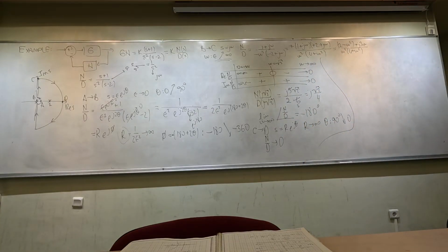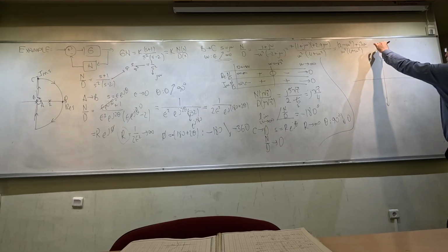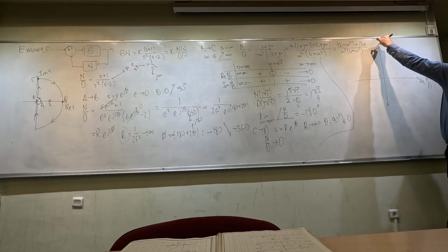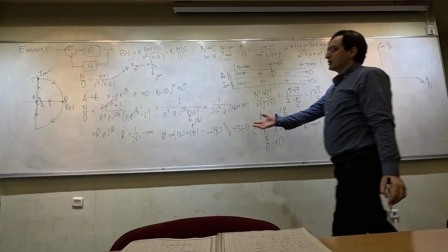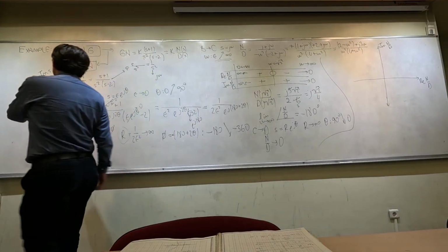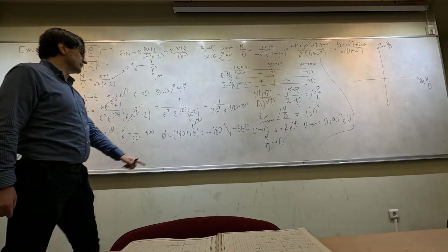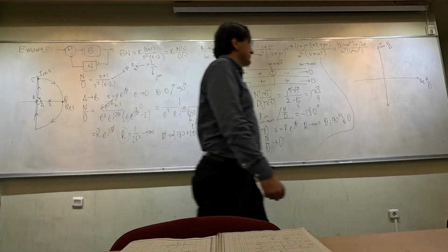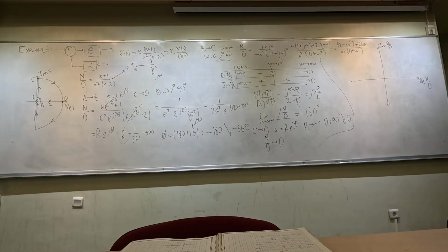And now we have completed the analysis for all parts of the Nyquist path, and now I'm ready to draw this thing. So I have real of N over D here and imaginary of N over D. We are going to start from the point A. Point A is going to be the start of this analysis. The radius is going to be infinite. The angle is going to be minus 180 degrees. I will say that it's going to be somewhere here.